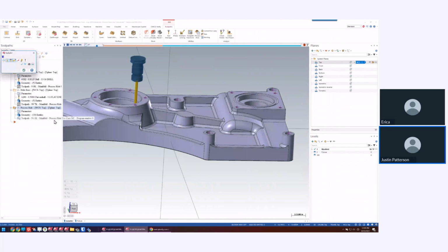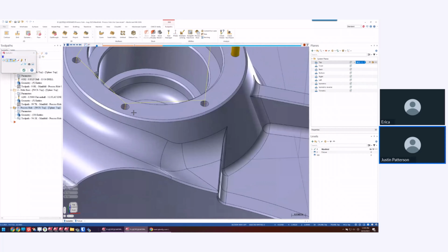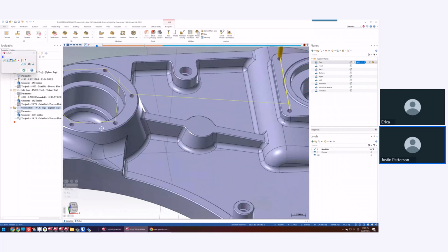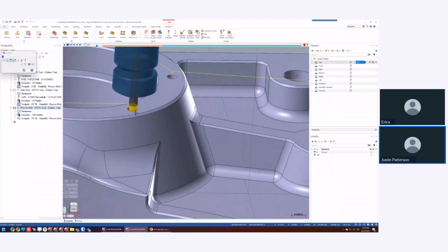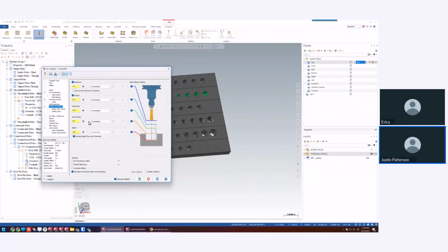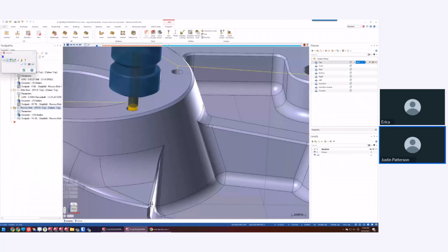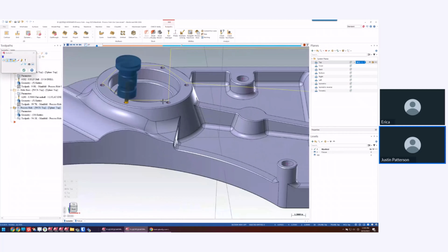So we drill down. And this one, you notice, I don't know if you paid attention, I brought this hole down 1 inch. But the thread mill I'm using is just an ISCAR thread mill. It only has 890 thousandths worth of threads. So when I defined it in my actual template here, let's go to the thread mill. You're going to notice that I defined this in the linking parameters to only go down 800 thousandths or 850, whatever you want. So it's still going to pull that information. Irrespective of how deep the actual hole is, I kind of limit it. That's more of a safety thing, in my opinion. That way, this hole was 1 inch, it's not going to try to shove that thread mill down the full 1 inch, just like that.